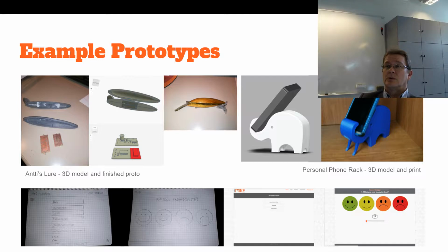It's an electronic lure. It has a microcontroller inside, a battery inside, and also a mobile phone vibrator inside. The idea is to run that vibrator once in a while to attract predatory fish, and it works.